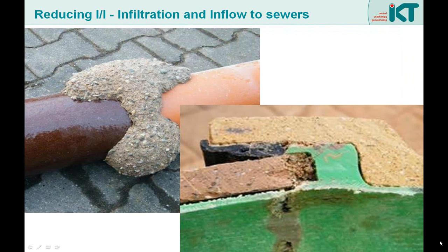On this picture, you can see the joints of the host pipe. Apparently, in some cases, the resin has entered the joint and even filled pores in the ground. Another effect was that at some joints, the adhesion and bonding effect between liner and host pipes were excellent. You can see it at the green liner.